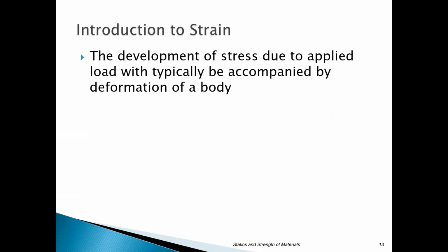So the next thing we want to take a look at is strain. Strain is another engineering concept we talk about when we're talking about materials. Due to the stress that is happening in an applied load, it's typically going to be accompanied by that body deforming. If you're pulling it, that body is going to want to stretch. And if you're pushing on it, it's going to want to compress. And if it's stretching, it's also decreasing. Let's say if you're pulling on a rod, the cross section is actually necking down. So there's two kinds of deformation going on: one in the axial sense and one in the lateral sense.